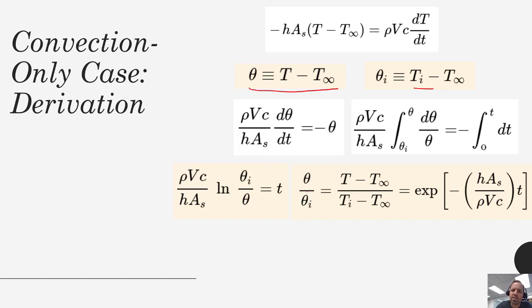But you could see with some simple reorganization of this equation, we could get pretty easily our temperature as a function of time. So if these are the particular circumstances, if it's a convection-only system, here's the solution. And in this case, you can do just plug and chug here. You need to know how long the simulation is going and some basic operating parameters of your system in addition to the initial temperature and ambient temperature, but then you've got your solution.